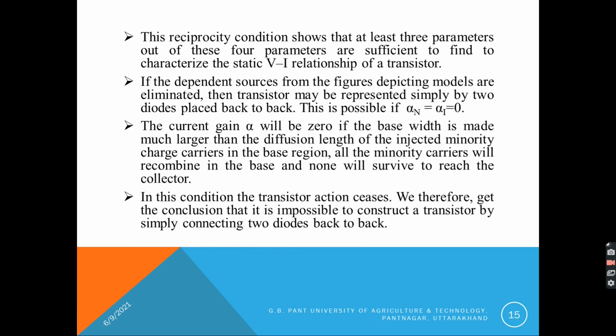This represents the reciprocity condition. This reciprocity condition shows that at least 3 of these 4 parameters are sufficient to characterize the static VI relationship of a transistor.